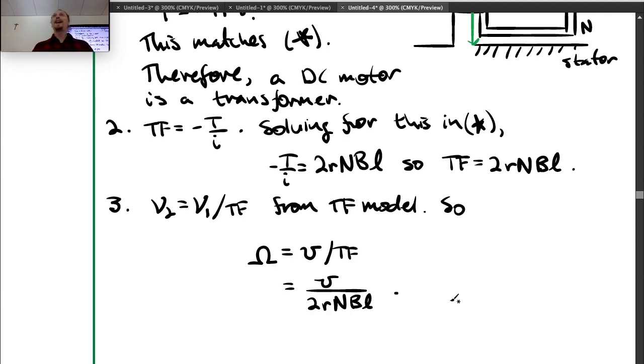So you can often get away with running full currents for a short period of time, but you've got to know how much time that's okay, and that's one of the things that I really like about this. You can start answering questions like, how long can I run at stall before my temperature gets too high in my motor? You can start answering questions like that, which is really, really cool. A lot of times it's difficult to answer those questions without a good dynamic model. You know that you can't run it indefinitely, but you don't know how long you can run it. So a dynamic model helps answer the questions about how long you can run it.